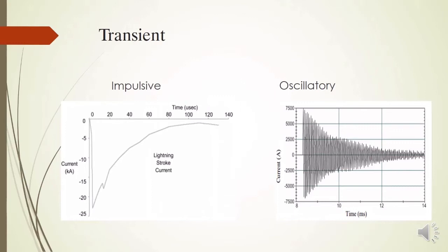The first power quality phenomena is the transient, or in other terms, the surge. Transient consists of two types, which is the impulsive and oscillation. The impulsive is a sudden non-power frequency change from nominal condition of voltage and current. It is unidirectional in polarity. It is normally characterized by peak value, rise and decay, or duration time. Most common cause of the impulsive transient is the lightning. The duration of the impulsive transient is from nanoseconds to milliseconds.